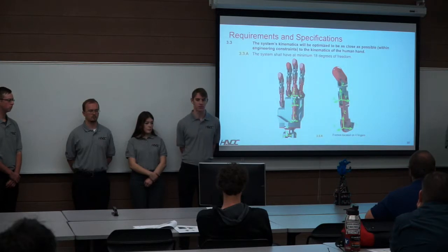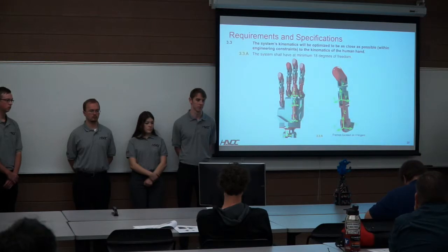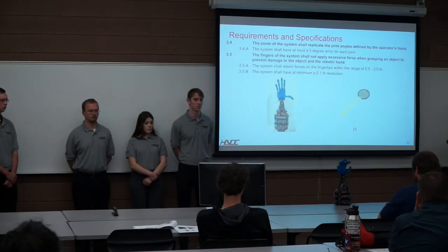However, we had to fix the fingertips so that we could reduce the number of servos we had to use, so that we could fit all these servos within our forearm because it was already getting larger than our specification. We also fixed the rotation of the wrist as so because we were mounting to a Sawyer robot.